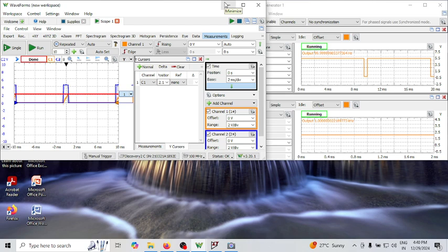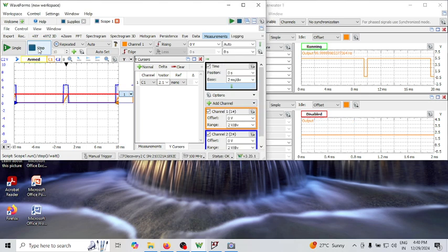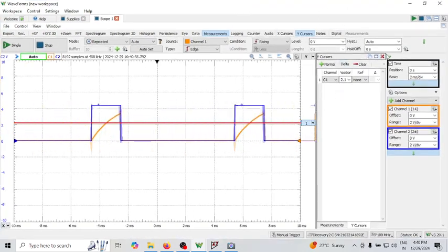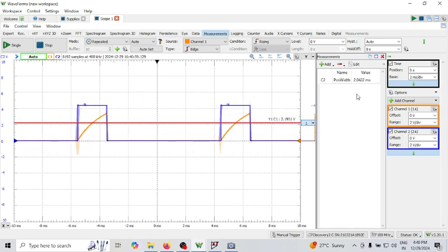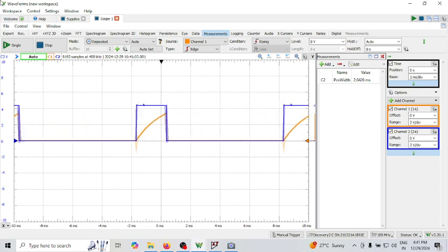That's what you're supposed to do when you're doing the experiment. Connect the circuit. Of course, let me show you one thing. Suppose your trigger signal is not less than VTL, what happens? So what I'll do now, I'll take out this external voltage. Let me just remove this. Now let me keep running it. You can see the moment I remove it, it goes up to 3.3 volts. Now this is fine. Let me take out this cursor also for clarity.